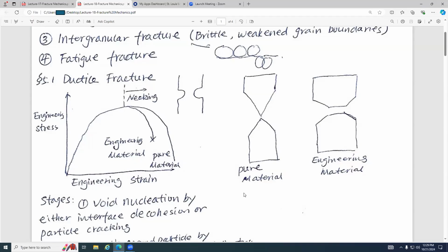You know necking, right, guys? Just like our neck, right? Can you tell me what is the difference between our neck and our body? The neck is smaller than the head and the torso. Do you guys agree? Necking is very, very intuitive. Originally it is so big, but at some locations it is necking. Necking means that at some location, the cross-sectional area becomes substantially smaller than other locations. So this is called necking, and then it goes down until it fractures.